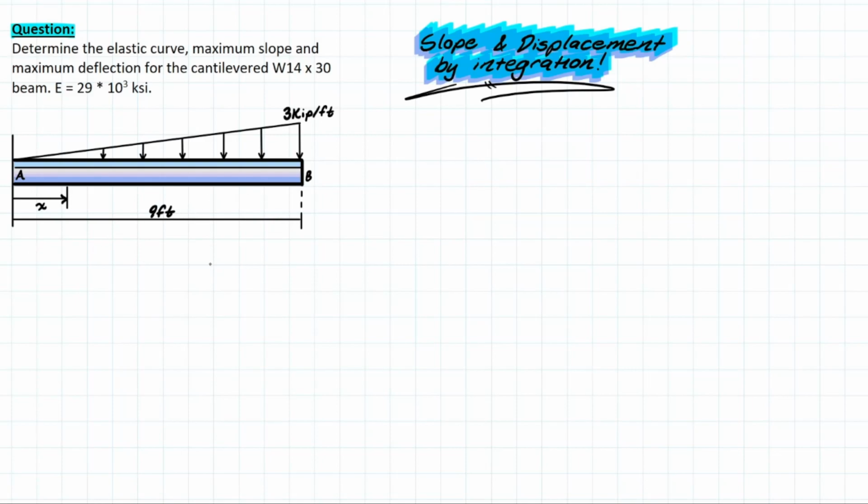And this all starts by first imagining what the elastic curve looks like for a member. Now, what is the elastic curve if we don't remember? Well, it's basically the predicted deformed shape of our member. And it uses the assumption that the deflections will be very small for our member, meaning that we remain in the elastic phase during loading. Therefore, we can then employ the elastic curve.